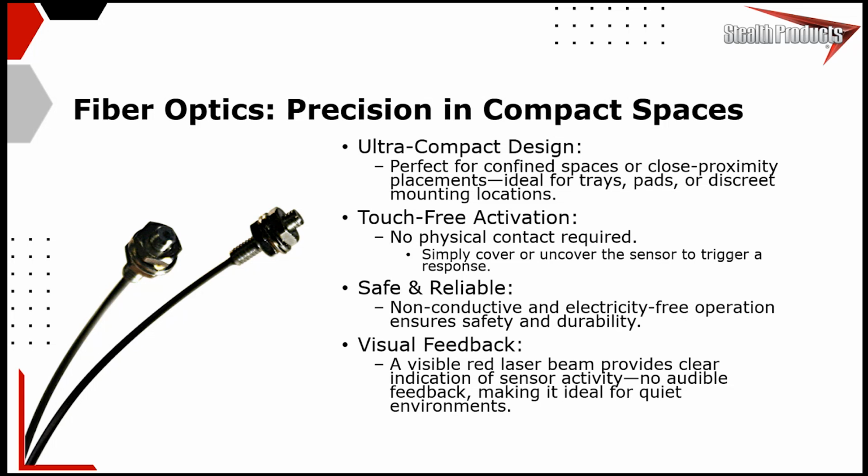But in essence, what happens with the fiber optic is you shoot a red beam of light out on one cable, and one other cable inside each of these tips here is looking for a reflection of that. You have about a 3 centimeter sensing distance in the ones we use that's going to be consistently reliable. And within that 3 centimeters, you've got 9,999 points of precision that you can adjust to. So they can be incredibly precise.